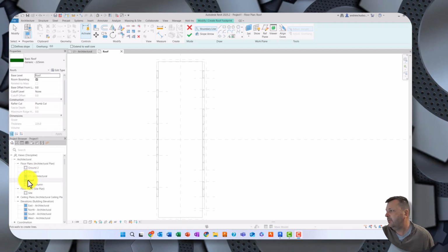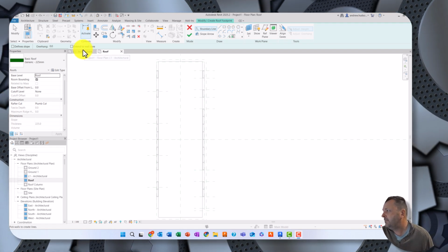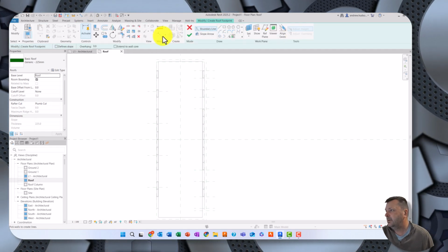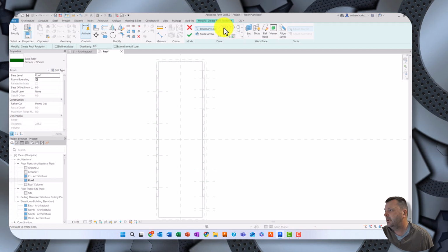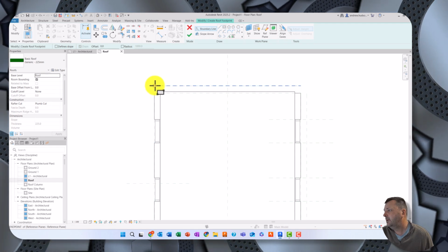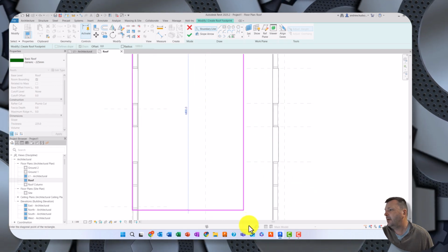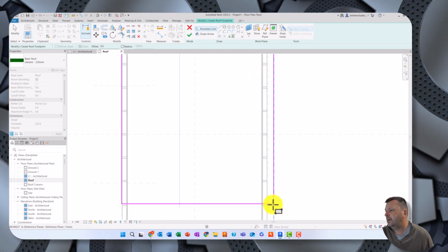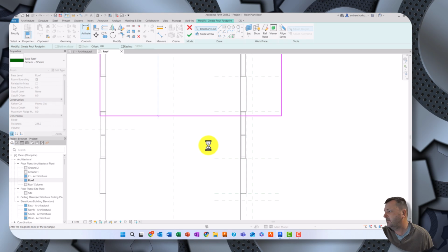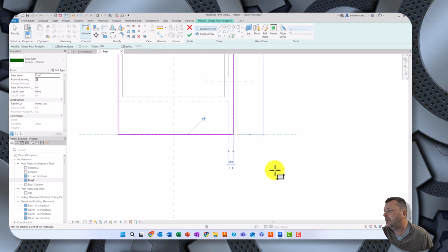So we open up the roof layer, double click that, and that brings up the roof project. Then we go to Architecture, select the roof, and it will open up this window here. Then we draw a rectangle, going from this corner here like that, scrolling all the way down, and we want that to come all the way out to that front point there.